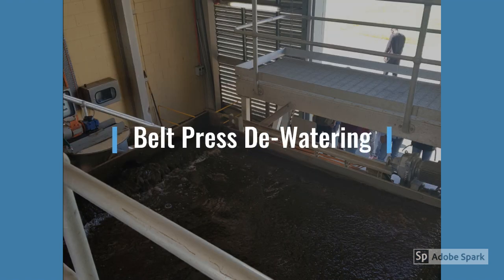This plant uses a belt press, whereby this sludge is compressed between two belts and a series of rollers to extract water and create a solid. As the technician stated, this belt press produces a product that is around 14% solids, meaning much of the liquid still remains within it. However, even the most efficient dewatering systems may only achieve 20% solids.